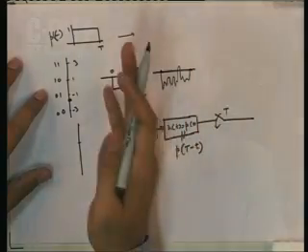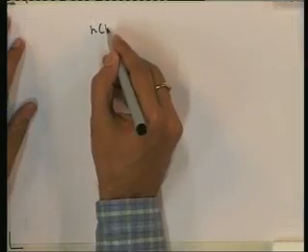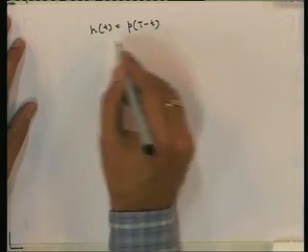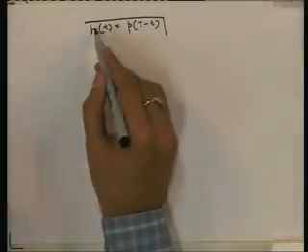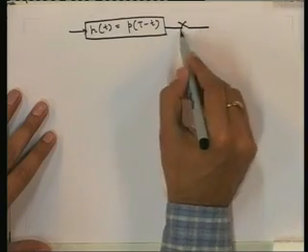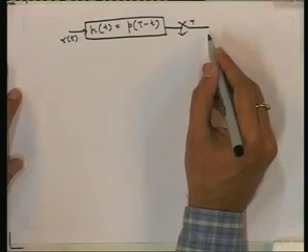For this particular pulse shape, the rectangular pulse shape, both PT and P capital T minus T are the same. So, it does not matter what you call it. But for other pulse shapes, it will matter. That we will see later. So, we will now investigate a generalization of this. In this case, we have seen that one choice is to take HT equal to P capital T minus T, first pass it through this filter, and then sample at T. This is one choice.